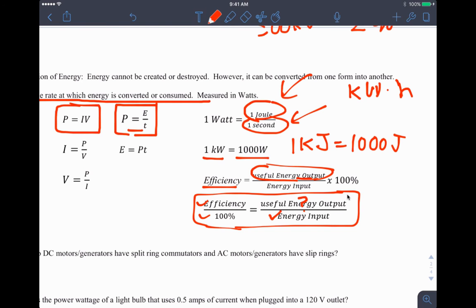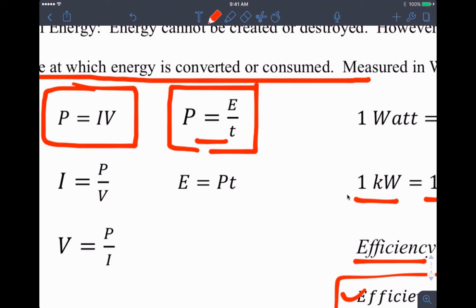And the way that they get that is it comes from this equation right here. Maybe I'll just zoom in on this. It comes right from this energy calculation. What power companies do is measure their power not in watts this time, but in kilowatts. And instead of measuring your time in seconds, this is the only exception that you'll ever deal with. You always deal with seconds unless you're dealing with this specific calculation. Instead of the time being in seconds, you get the time in hours.